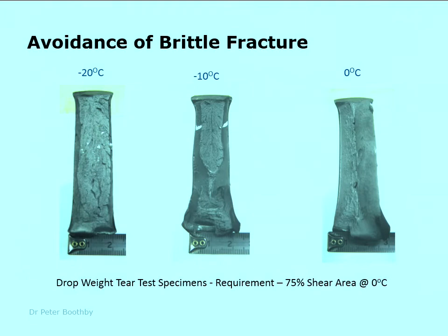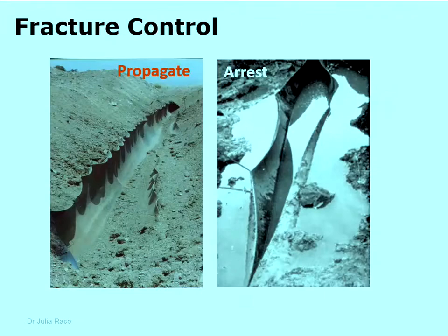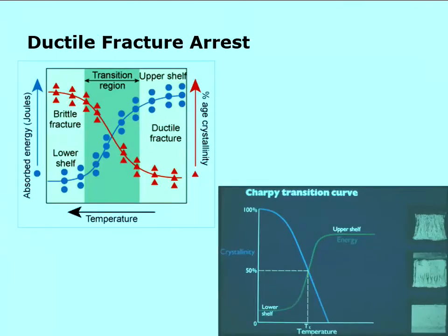Again, if there's any of you here who are interested in material properties, the issue we've got with Charpy tests at the moment is that the pipe manufacturing methods now are so good that if you take Charpies from them, you can't fail the Charpies, which is an interesting concept, but it's not really telling you anything about how safe the material is. The test isn't working. So for high quality pipe materials now, we need another QA test which is going to provide the level of assurance. And the fact that the Charpy test doesn't actually fail is not really good enough.